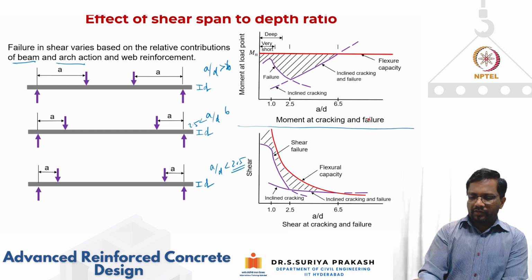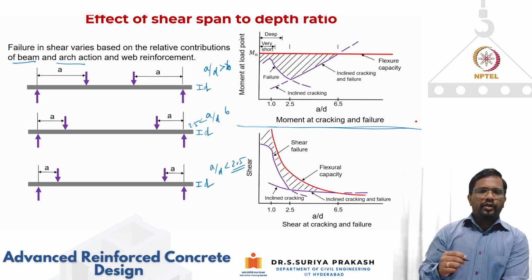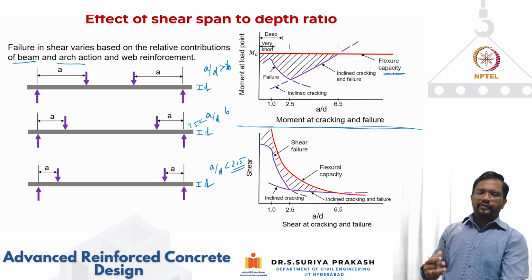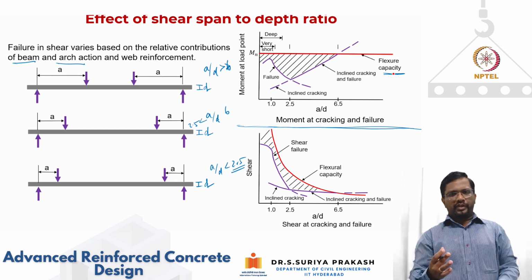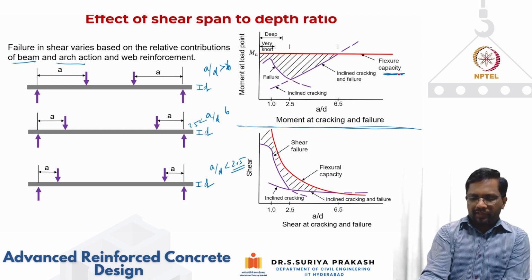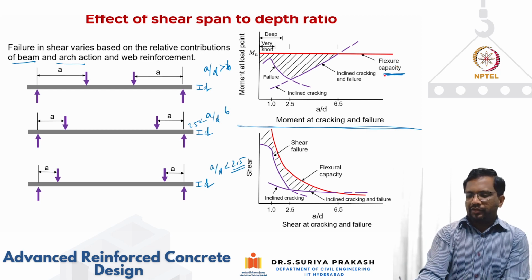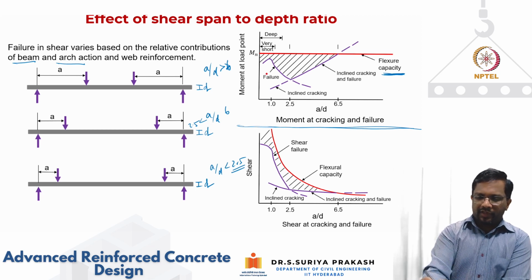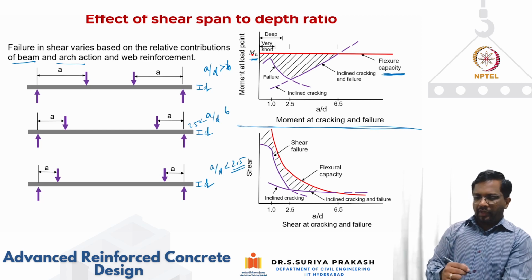Let's focus only on this top figure here. For each section, depending upon the reinforcement, my flexural capacity can be calculated. So let's say I'm giving the reinforcement along the length of the beam. You do your moment curvature analysis or your IS 456 calculation. Let's say that this beam is having a constant tension reinforcement. So at every section, it is going to have a constant flexural capacity. Let's keep that as the capacity of the beam in red color.